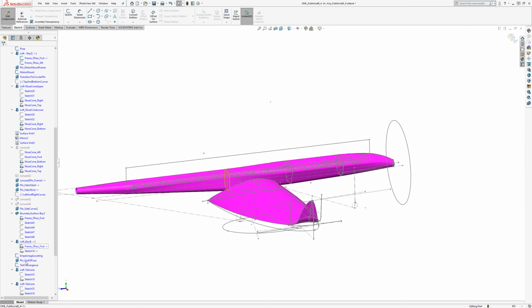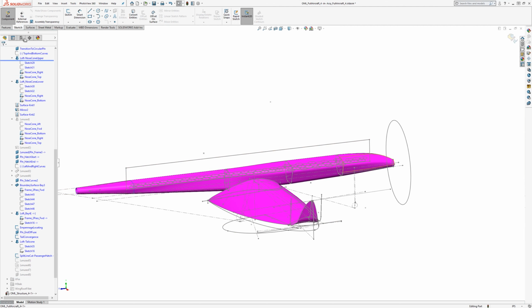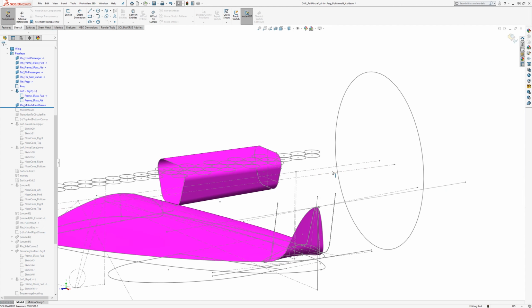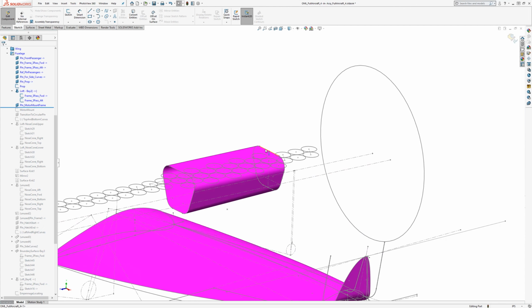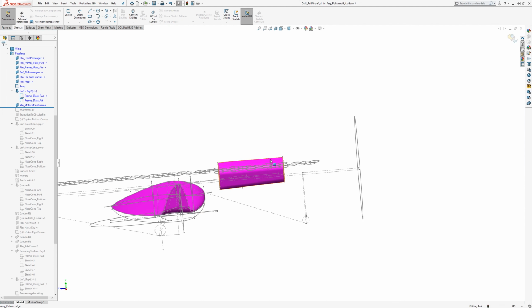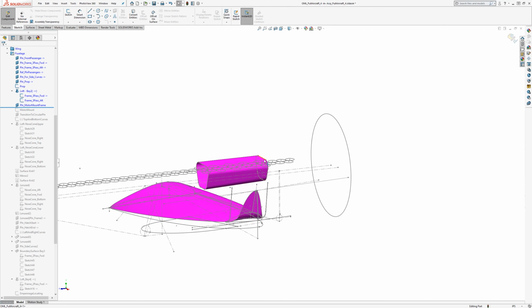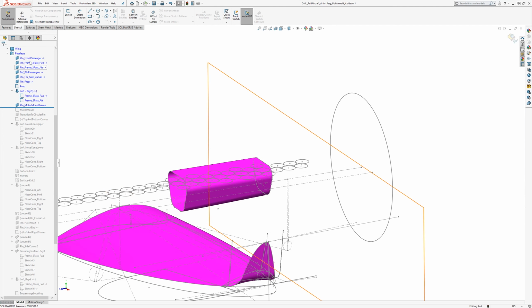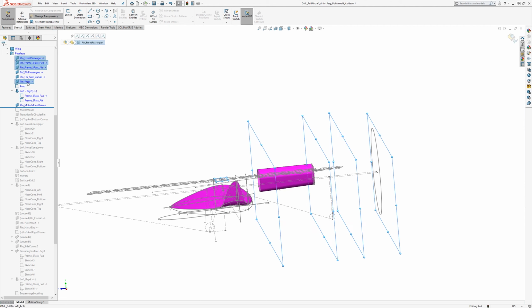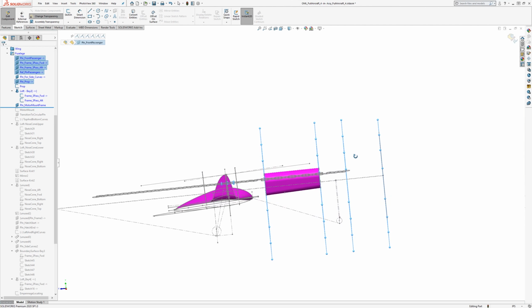This one gets a bit awkward to roll back, just because in a fuselage you're using the same frame sketch for neighboring parts. If we call each of these segments of the fuselage bays, then each neighboring bay uses the same frame sketch for the forward part and the aft part. So if I were to do this again, I would probably make a plane for each transition where the fuselage makes a